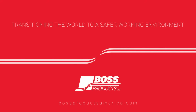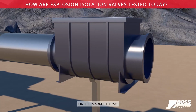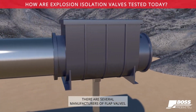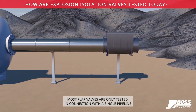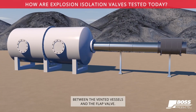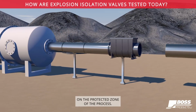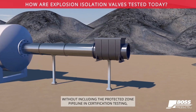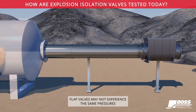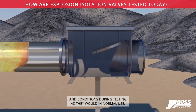This is a video of our explosion isolation valve, the VigiFlap, and how they're tested today. On the market today, there are several manufacturers of flap valves. Most flap valves are only tested in connection with a single pipeline between the vented vessels and the flap valve. These tests do not include the pipeline on the protected zone of the process. Without including the protected zone pipeline in certification testing, flap valves may not experience the same pressures and conditions during testing as they would in normal use.